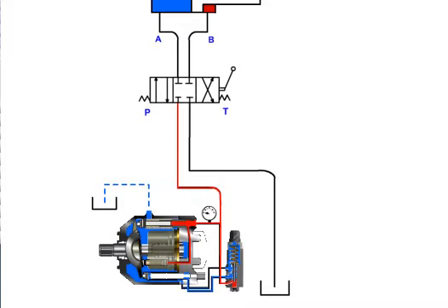In this example, we've used a pressure-compensated pump. It is helpful to understand the functionality of a piston pump. If you need to review this, return to the Pumps menu and go to the animation for piston pump. In this example, when the control valve is in the center or closed position, the pressure forces the compensator spool to shift up against the spring setting, allowing the pressurized fluid to shift the control piston and the swash plate